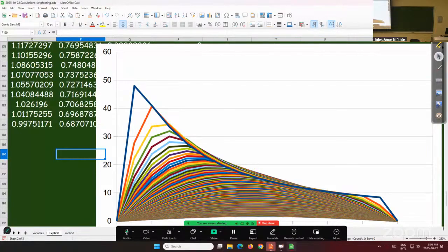So the initial pore pressure distribution, which you would estimate as the blue line, just using the elastic theory, the Boussinesq method, would not give you the most critical stress distribution or pore pressure increase. Okay, so that's an important little detail to keep in mind when you're doing these analyses.